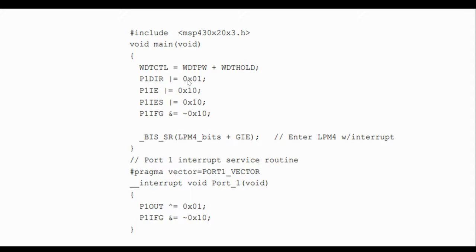Okay, you configure. You remember I taught you guys how to do bit masking. This n equates to negate of whatever this value. It means that this is a mask reset, and this is a mask set. It means you only affect that pin that is selected, whereas the other pins you do not touch. Now P1 direction means you set the first pin of the port as output.